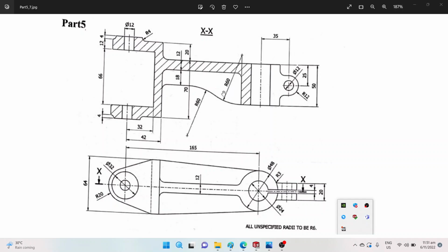Now, when I approach this problem, before you even start SolidWorks, you need to spend some time to study the drawing. When you study the drawing, what are you actually looking out for? You're trying to look out for where your datum planes will be. How do you intend to start? You can actually start on different features at a time, but wherever you start, the datum planes should more or less be the same.